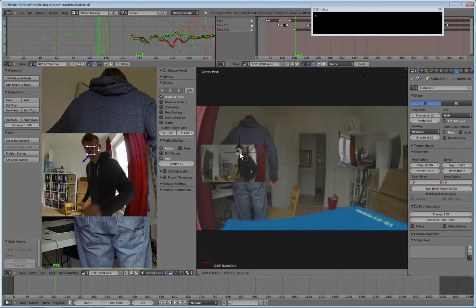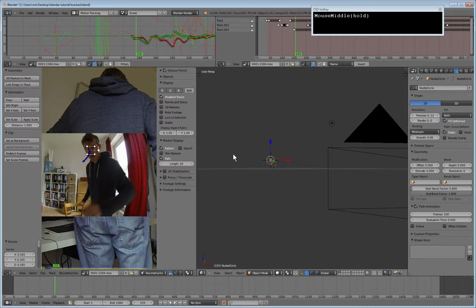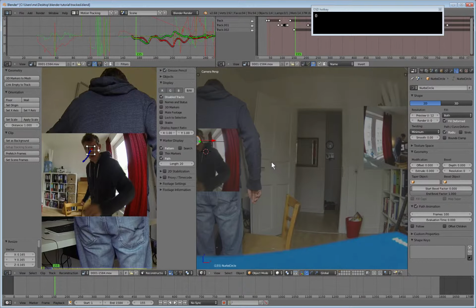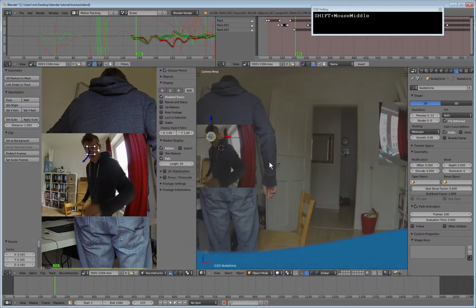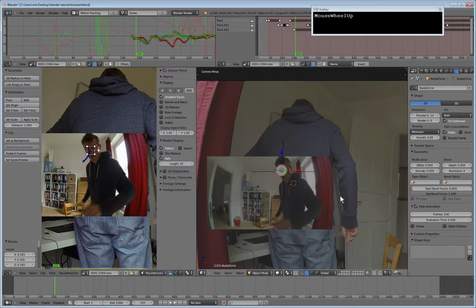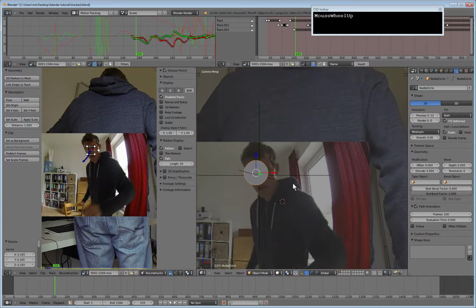And since this is the absolute biggest circle I need over the whole video, I'll just try this and zoom in. Whenever this happens, you can return to the camera view with 0, and with Shift middle mouse button, you can drag the scene.